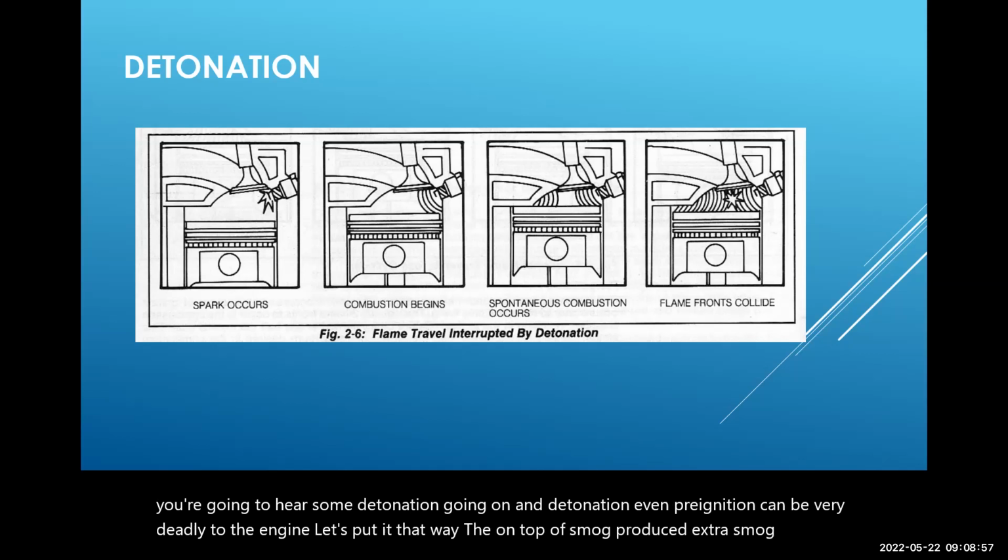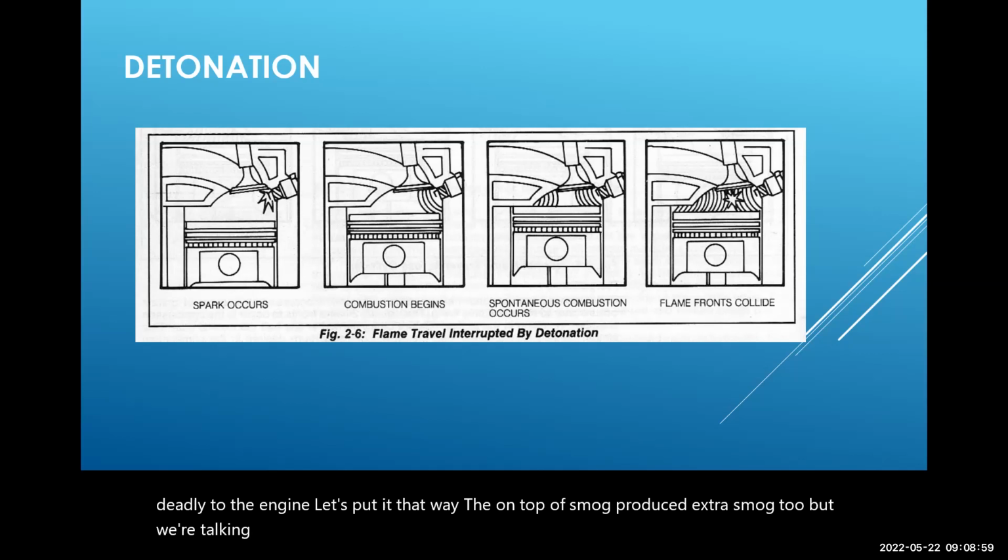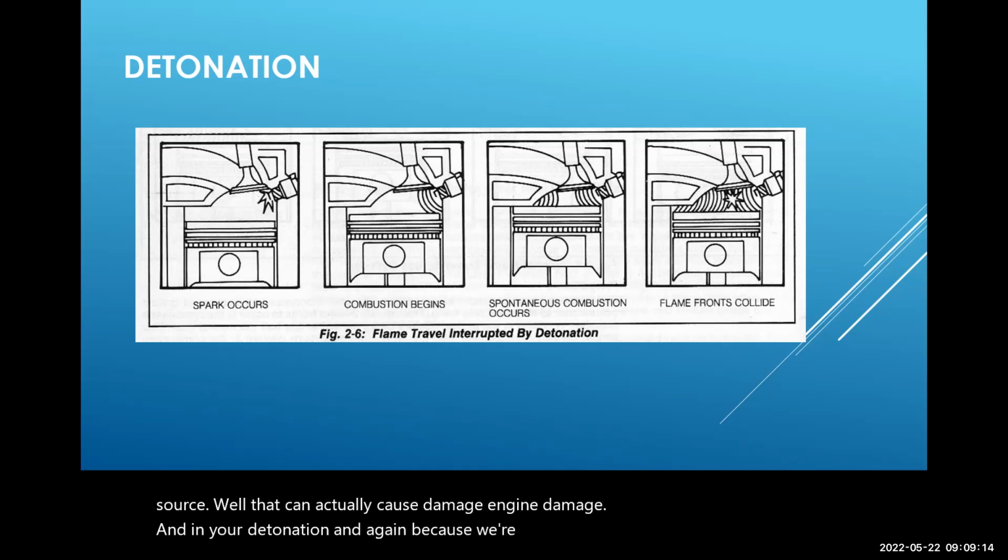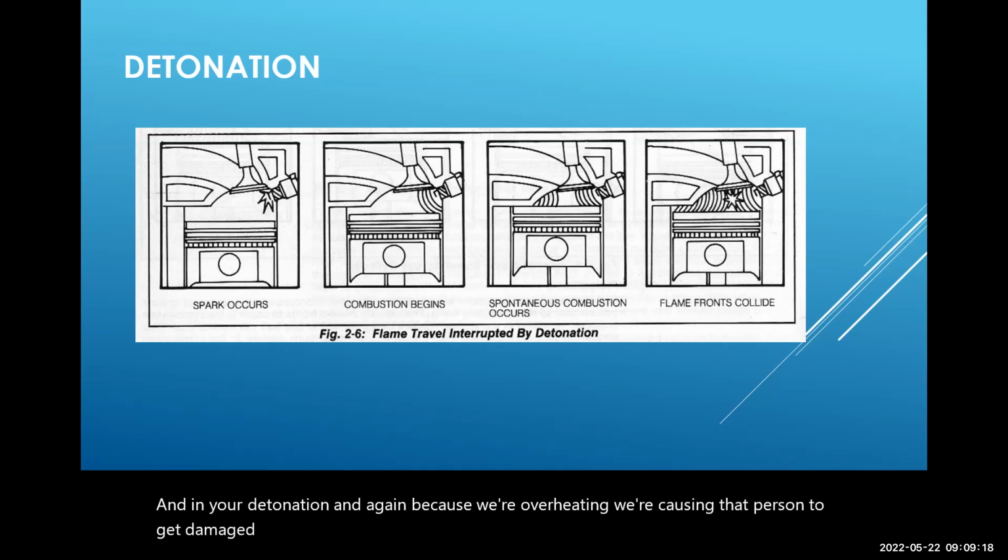In pre-ignition, where you're firing from a heated source, that can cause engine damage. And in detonation, because we're overheating, we're causing the piston to get damaged, and we could have cylinder damage too. I've seen all kinds of holes in the tops of pistons because of detonation.